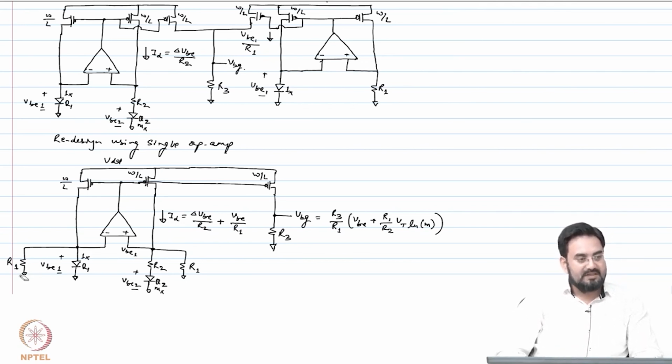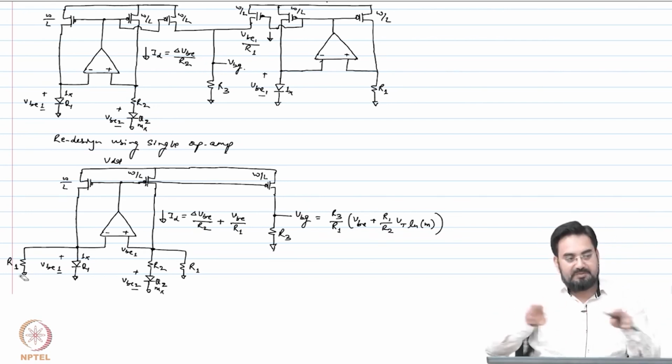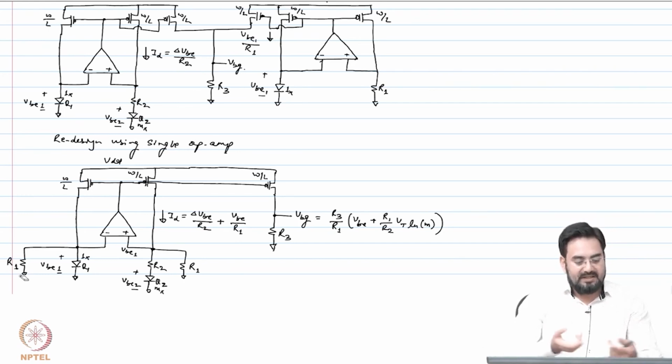So not only the current mirrors, but these resistors also have to be matched. So R1 R2 is the another thing, because we want to maintain the ratio, so they need to be matched. Now we have a 2 R1 actually here, so they have to be perfectly matched. So any error between those two or mismatch between those resistors will also introduce error here.